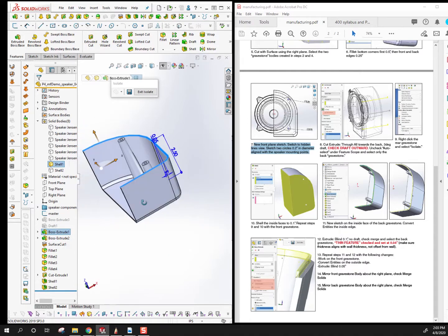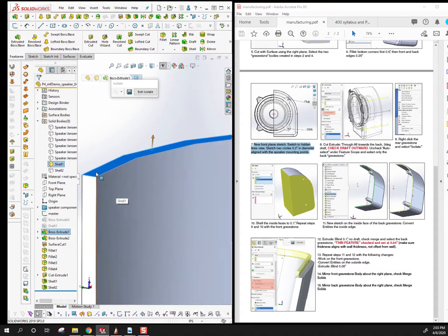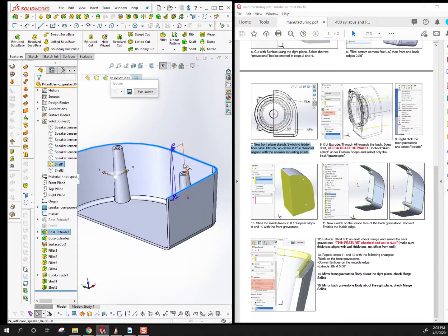If you want to create planes, I would do that from the master sketch. I would not create a plane literally based on this face because that's an extra step that's not necessary. If you are inserting a new plane based on this face, you may as well just sketch directly on the face. I can understand creating a new plane if this face is curved, or if you want to tie it to the master sketch, I can understand that.